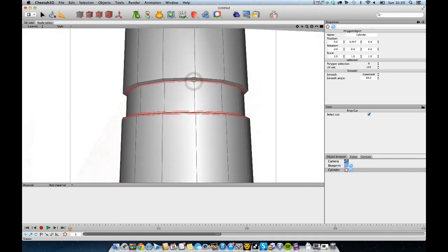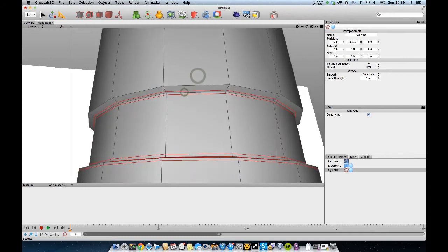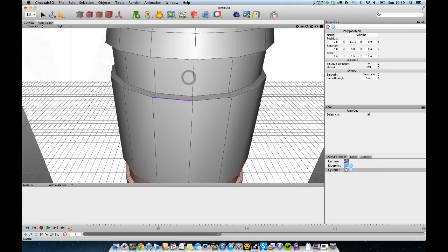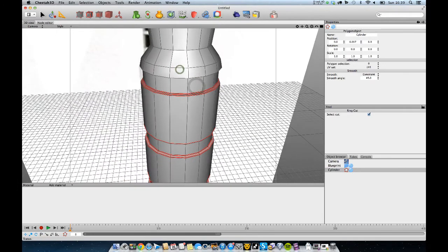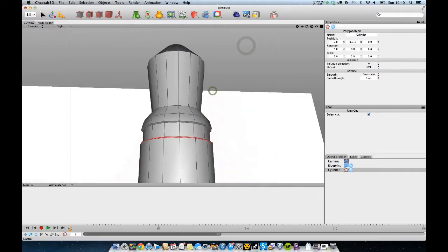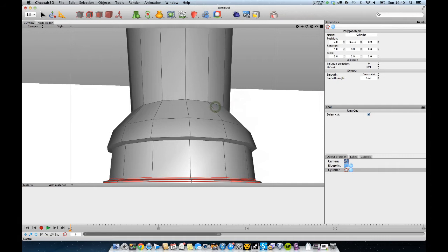Another cut there, one there, and there, and there. You can see what I'm doing. Going in nice and close. Again, it's not about perfection. If I was going for more 100% accuracy, I'd probably use the bevel tool and have a certain step amount set, just to kind of keep everything the same. But working at this level and for this kind of render that I'm doing now, I'm not that bothered.